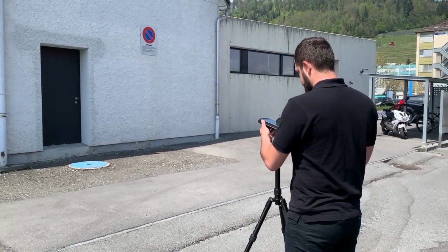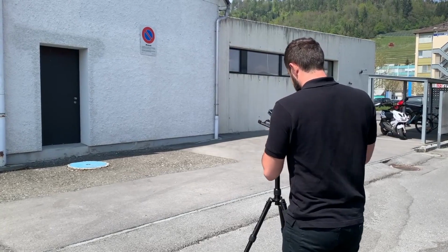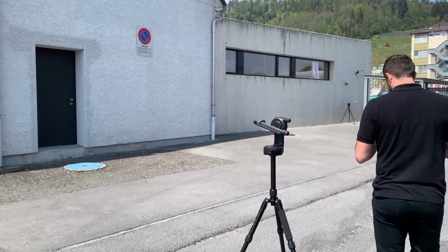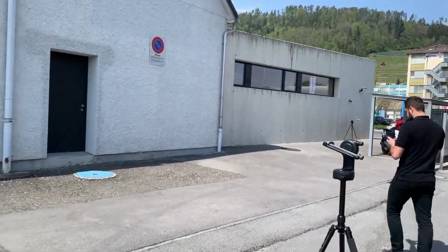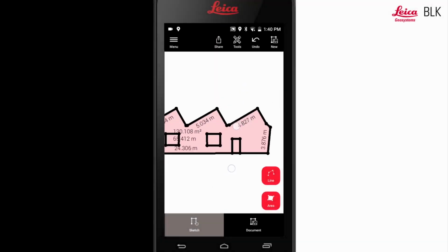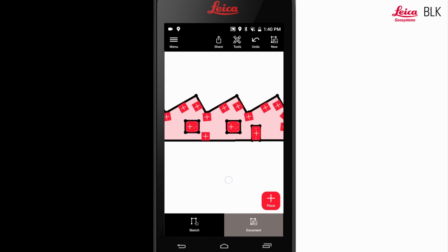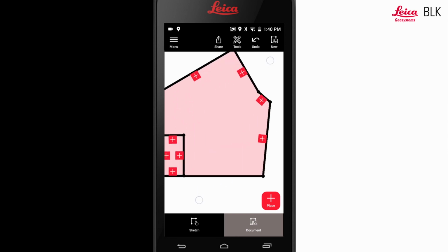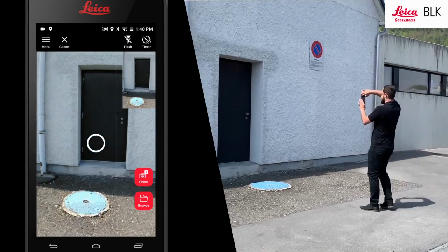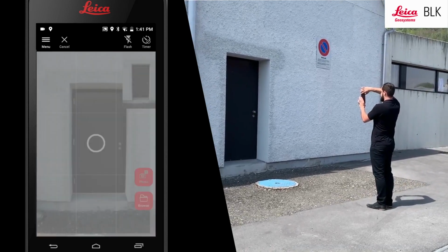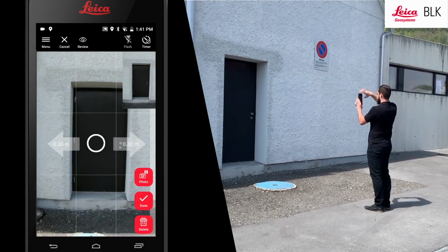To do this, take the BLK3D from the DST360 adapter and approach the wall you want to capture. On the display, select the Document tab and then select the plus icon of where you want to add an image to. If the icon is not in the spot you would like, you can create a new one or move an existing one. Step to your object and capture it. Image will be automatically saved to your selected place icon.